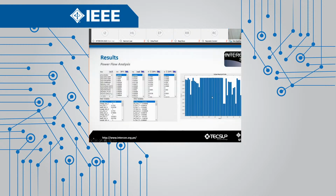Before the results, when you have made your graphic representation, you do the eigenvalue analysis. But you first need to perform the power flow analysis. In that case, the power flow analysis in PSAT provides us some results like voltage, angle, active power, reactive power, and the state variables.